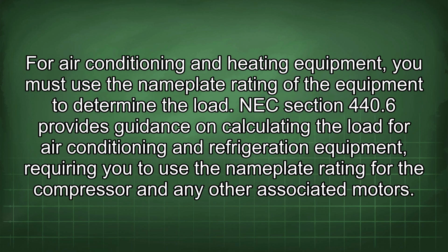For air conditioning and heating equipment, you must use the nameplate rating of the equipment to determine the load. NEC section 440.6 provides guidance on calculating the load for air conditioning and refrigeration equipment, requiring you to use the nameplate rating for the compressor and any other associated motors.